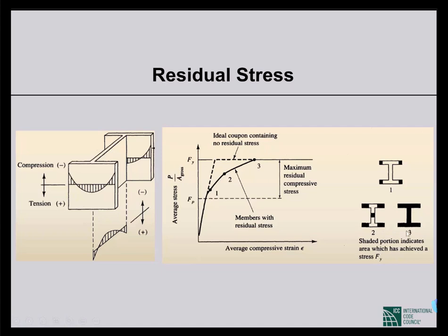But in this process, there are compressive stresses at the edges of the flanges and the middle of the web, and in other places there are tensile stresses. Due to these residual stresses, when actual load comes onto these sections, the additional compressive stress causes local buckling.